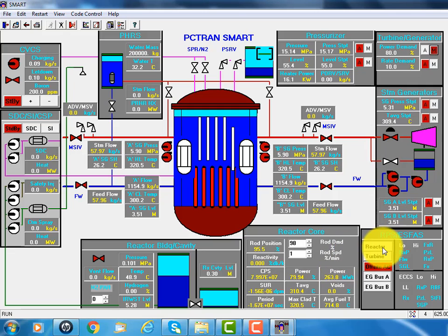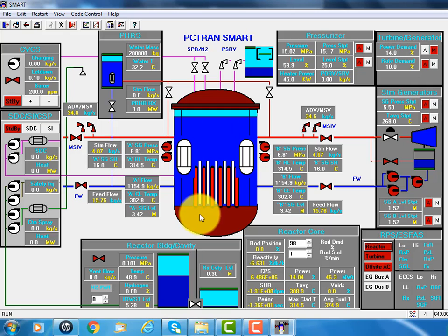In case we shut down the plant, we can simply click here and all the control rods go in, and the system will be stabilized in a post-trip condition. The heat removal after reactor shutdown is by the condenser. You see the turbine stop valve is closed. The turbine was pink, symbolizing rotating, and now it's blue, symbolizing it no longer generates electricity. Most of the steam will go to the condenser.